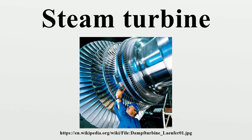In a double-flow rotor, the blades in each half face opposite ways, so that the axial forces negate each other but the tangential forces act together. This design of rotor is also called two-flow, double axial flow, or double exhaust. This arrangement is common in low-pressure casings of a compound turbine.